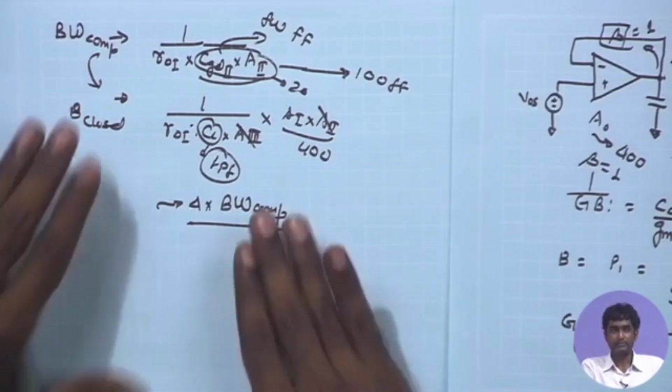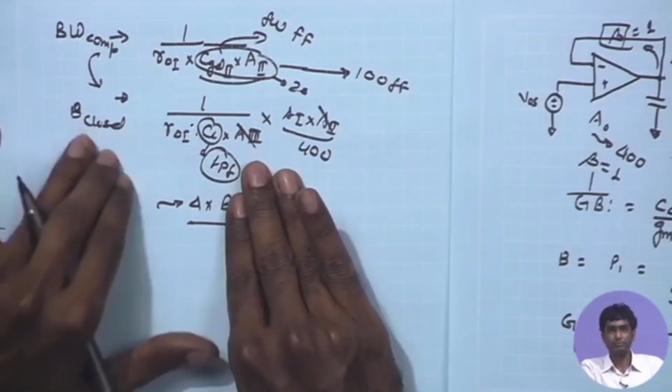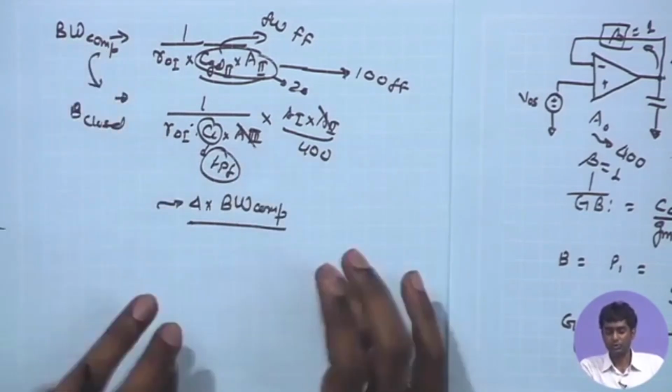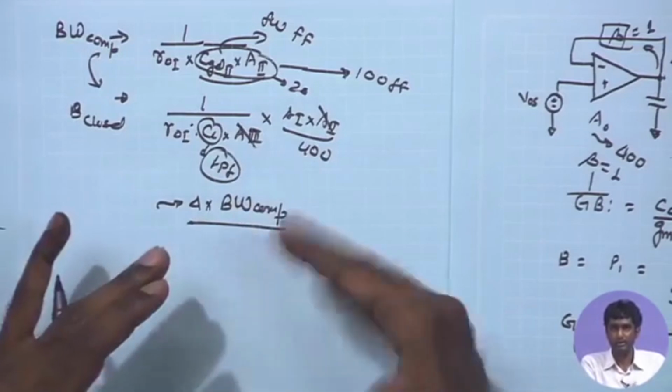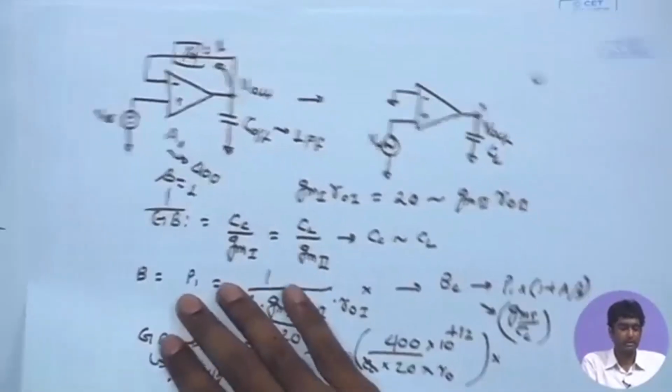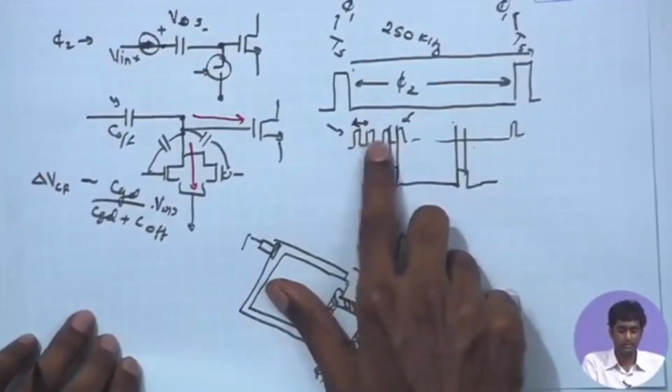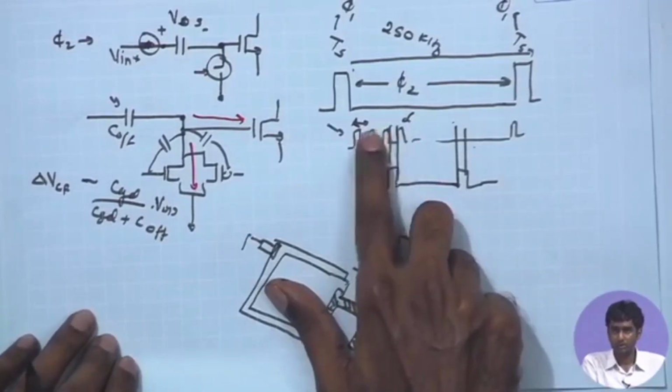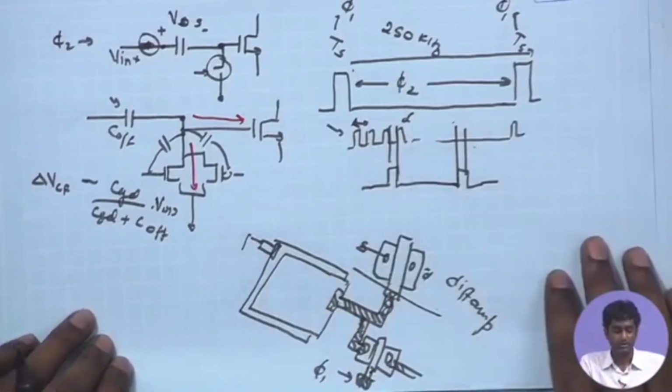And then we discussed the case where the bandwidth goes down and becomes smaller than this, what is the implication, and how to handle that by modifying the control in the offset cancellation loop, rather than using just one, using a larger number of these clock pulses for the offset cancellation.